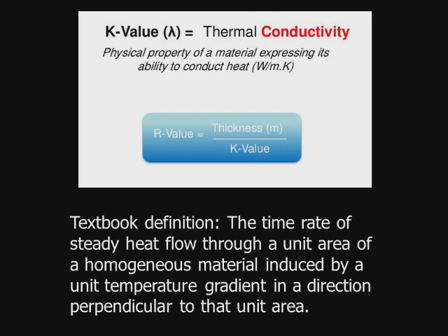Now, the interesting part about this is that the K factor is not determined by thickness. The K factor for a material 1/8 inch thick is the same as it is for a material that's 1 inch thick. It's just a small little fact. When you start to talk about C value or C factor, that's where thickness comes into play. But again, the point of these definitions is strictly to get across that R value, K factor, U factor, all of them are material characteristics. They are absolutes, and they have units of measurement.